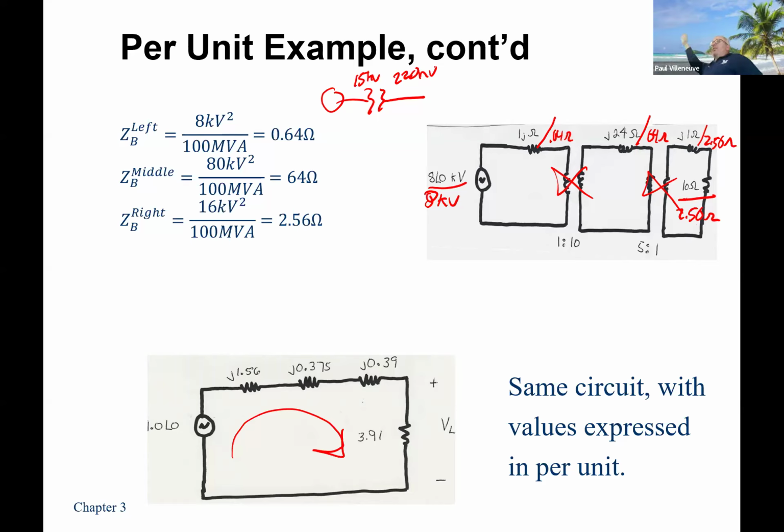So let's say you get 10 transformers that are 50 MVA. If you use 50 MVA, you won't have to convert things so much. And we'll see why that makes sense. For V base, usually you just pick one wherever it's convenient. There's no advantage to trying to be selective about it. You can a little bit, but most of the time you can't really do anything.